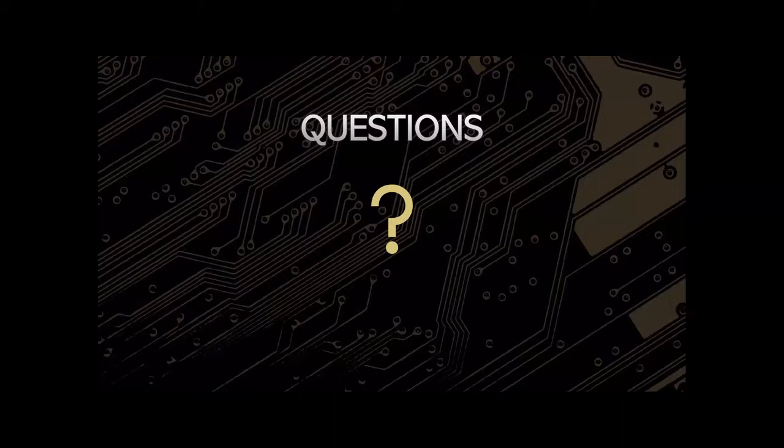And I think something that helps, actually probably the last two questions together, is having a netlist file. If you have a netlist file and you send that, most questions that we have, whether it lines up or not, we're going to waive it, because that IPC file that you created confirms that everything on my side is working. I've double, triple checked, and this board is exactly the way I want it. That is going to be our kind of white flag of saying, go ahead and proceed with the build. You don't need to put it on hold.